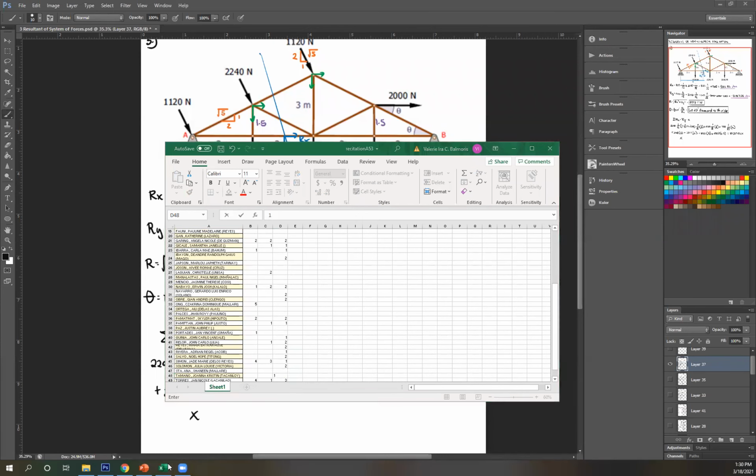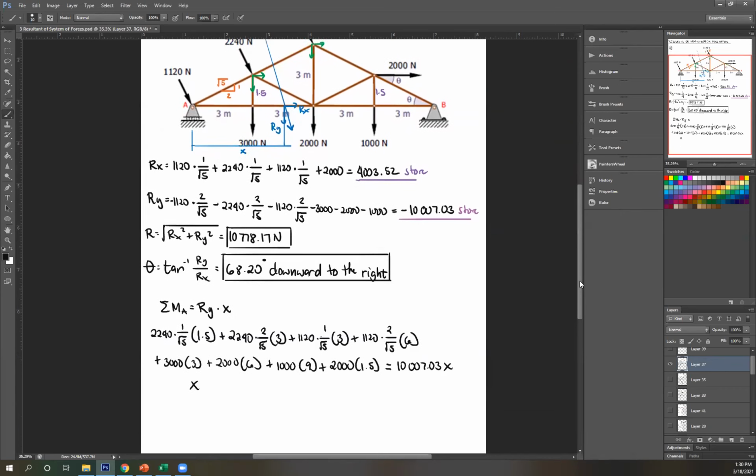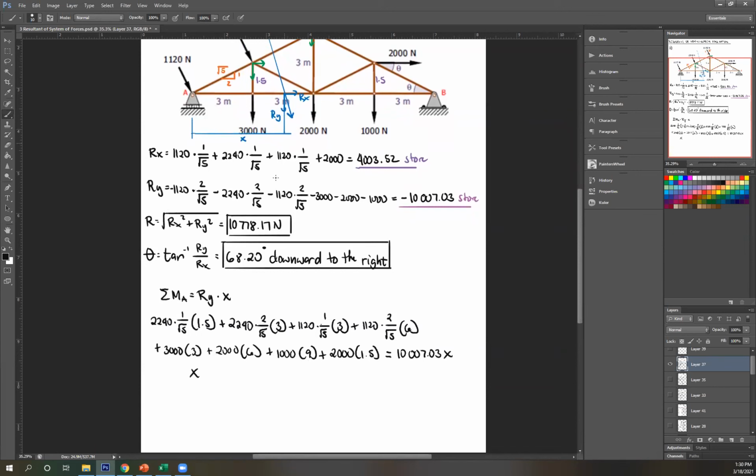Okay. So it's 4.80 to be exact. 3,000, 1,000, 1,000. Okay. So 4.80 meters to the right. So I got a positive answer for x. So that means my assumption for the position for resultant is correct. So it is indeed 4.80 meters. And then to complete this, indicate to the right of your reference point. To the right of A.